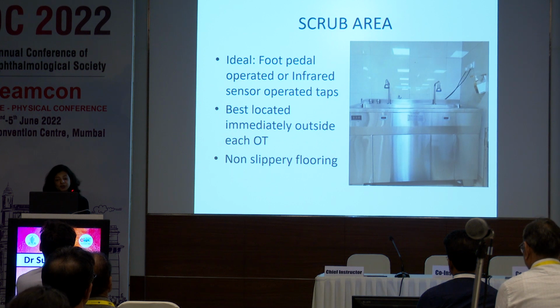Scrub area should be located immediately outside each theatre. The flooring in this area should essentially be non-slippery, and taps should be either foot pedal operated or elbow operated or infrared sensor operated.